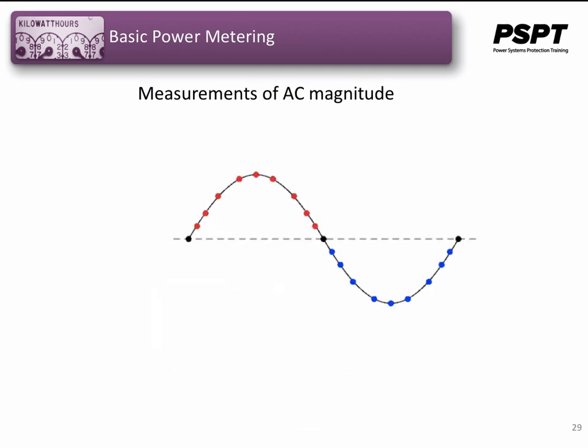Another way of expressing the magnitude of a wave is to mathematically average the value of all the points on the waveform graph to a single aggregate number. This amplitude measurement is known simply as the average value of the waveform. If we average all the points on the waveform algebraically, that is, to consider their signs either positive or negative, the average value of most waveforms is technically zero because all the positive points cancel out all the negative points over a full cycle.